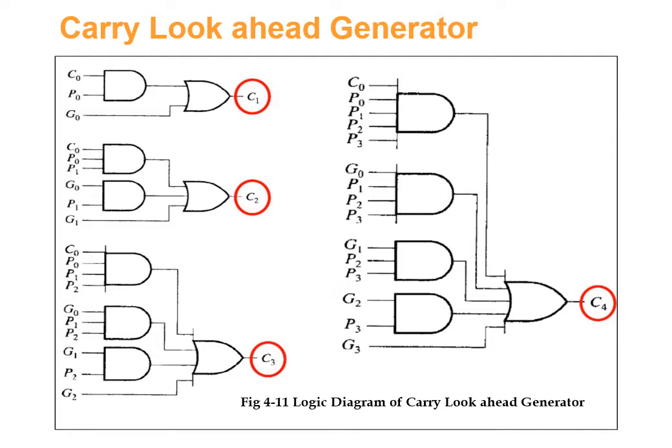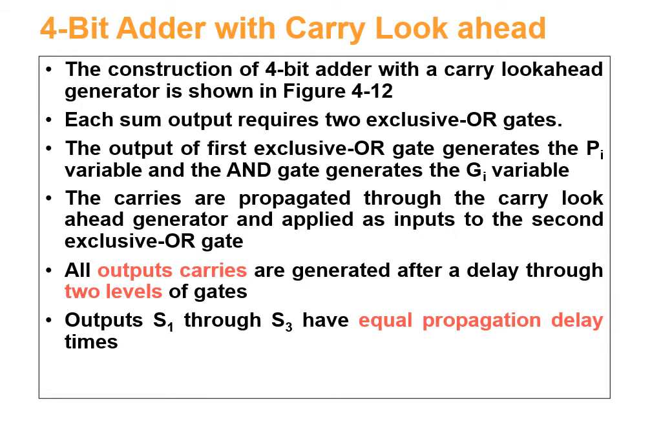The construction of a 4-bit adder with the carry look-ahead scheme is shown in this figure. Each sum output requires two exclusive OR gates.